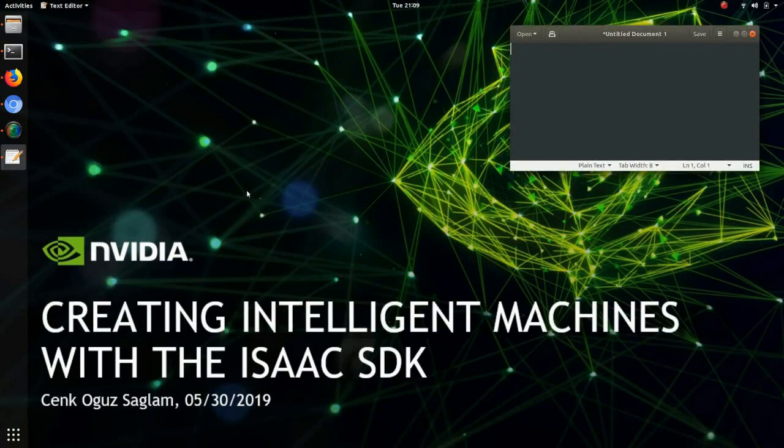So let's summarize what we did together today. So we modified the C++ codelet, we wrote it together, and although Python codelets are supported in Isaac, we prefer C++ codelets for performance. Then we modified the app.json file that determines the application to reflect our changes in C++ codelet. We use website to track what our robot is up to and change the parameters as we desire. Then we showed that moving from test to simulation and from simulation to real is very easy with Isaac. We looked at a couple of sample apps together, and there are more if you are interested.